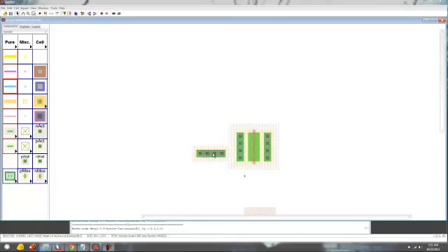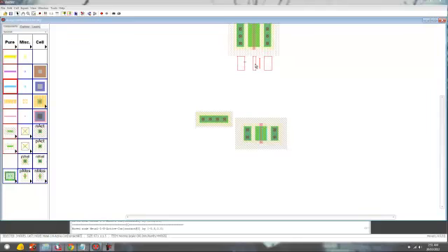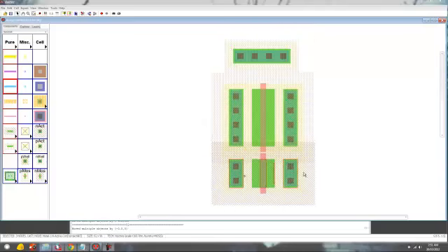And when you are done aligning, select all and Ctrl J to rotate the PMOS. Then align the N well above the PMOS. Do the same to the N, spacing 3. Align them. Select the whole diagram and Ctrl J, rotate it. Make sure you align with the PMOS you just did just now.